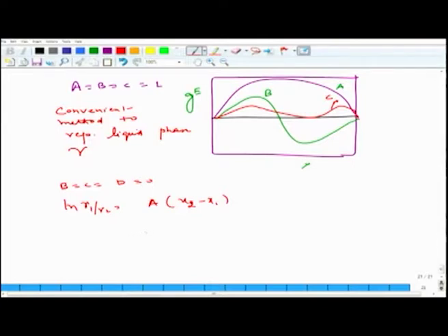So, for a simple system where you have similar sizes, the way we have used the one-constant Margules equation, you can also use the same way for similar systems such as toluene, hexane, benzene, isooctane.